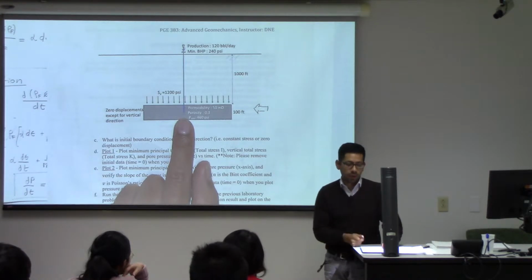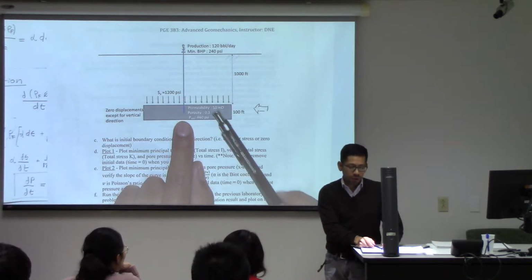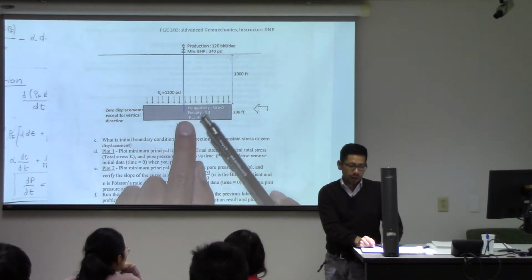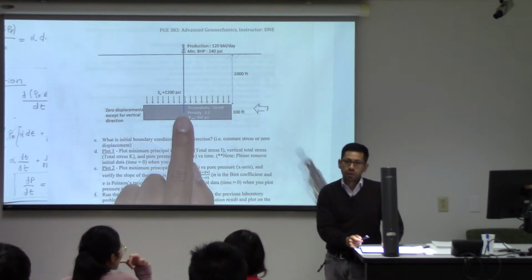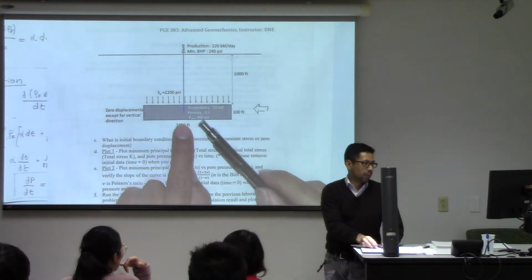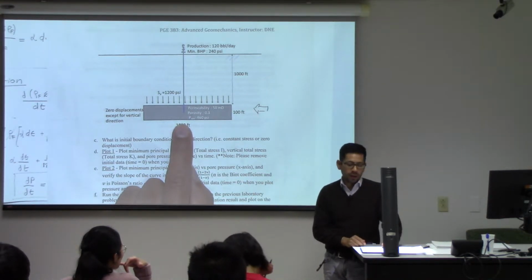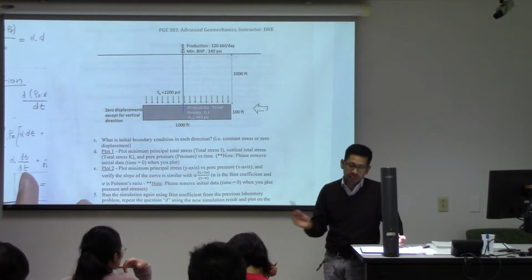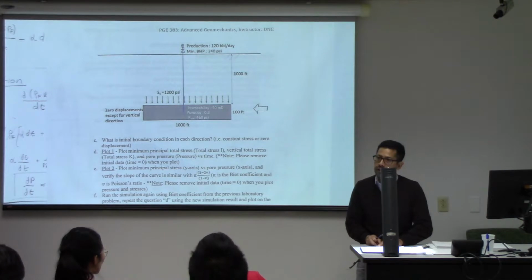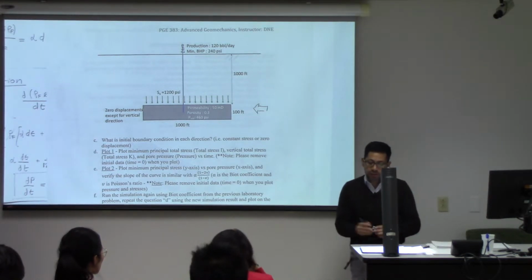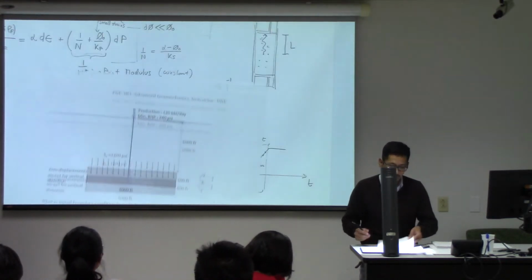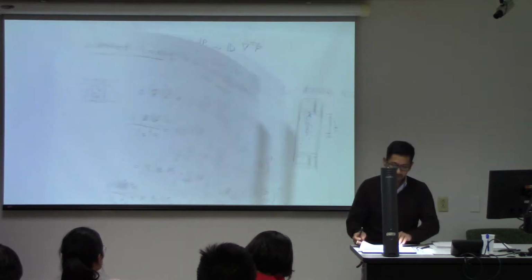So his argument was that the diffusion time was too long for this entire system, so you could capture rapid changes of stresses in the order of a few days or a few weeks by measuring the wellbore pressure. It makes sense. I don't know how precise that could be, but that makes sense. So let's talk about some other examples of undrained loading, and we'll come back to this one later on.